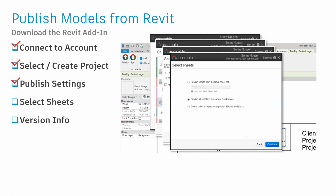We always suggest publishing the sheets, but if your publish process is taking a long time, sometimes that can be due to a lot of sheets being associated with it. So in that case, we suggest publishing sheets from a particular sheet set or not publishing sheets at all.